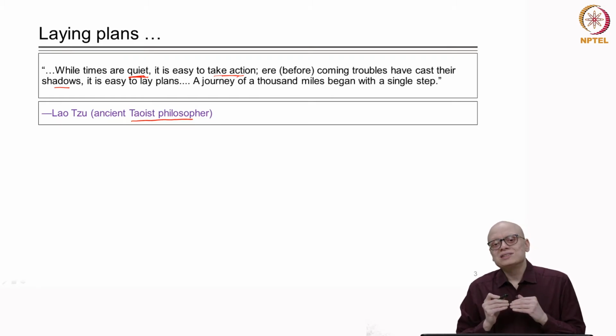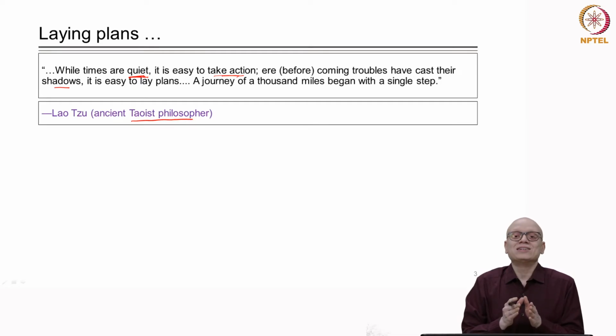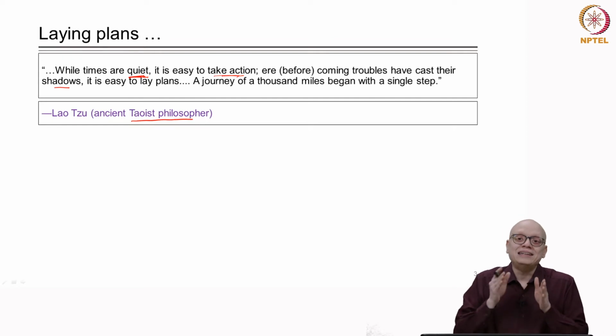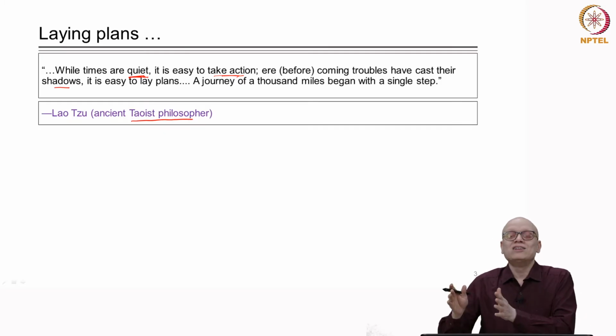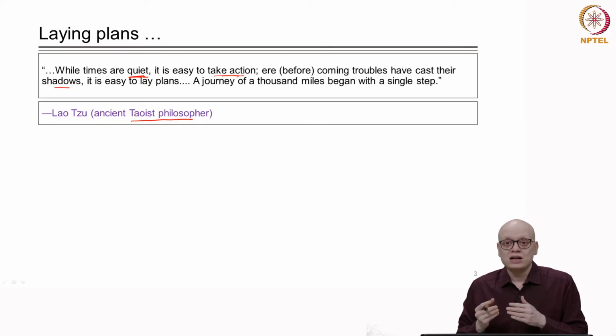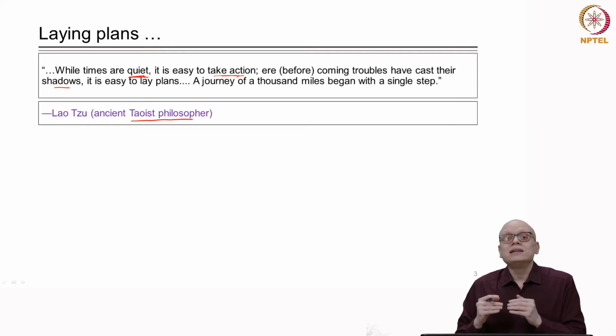Why do we want to do chip planning at the early stages of physical design? The reason is that at that time we have not yet decided many things about the physical layout of our design, and therefore there is a lot of flexibility. Therefore, the most important decisions related to physical design must be taken at the beginning of the design flow, during the chip planning stage. If we take a wrong decision at this point, that wrong decision will percolate throughout our design flow and impact the final QoR. So, right at the beginning, when we start the physical design flow, we should take the most important decisions related to physical design, because it offers a great deal of flexibility.